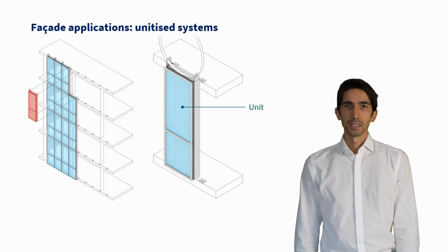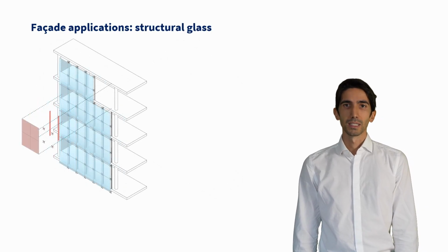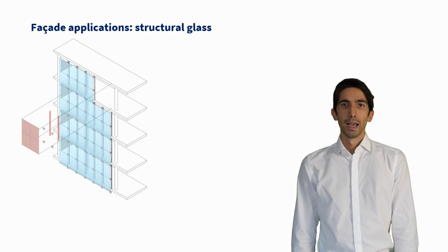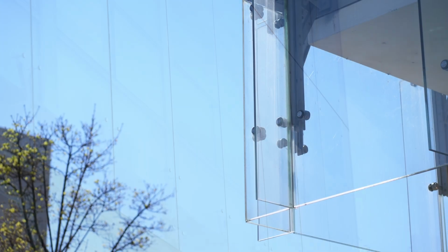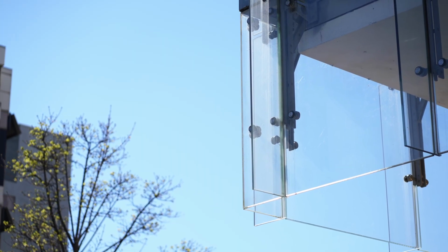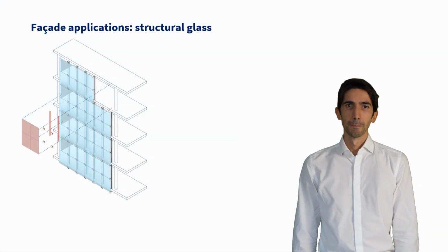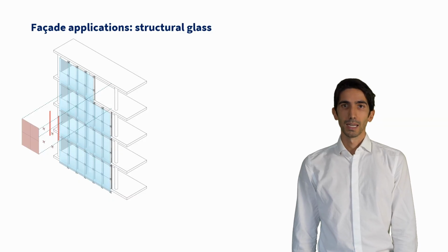Finally, the structural glass facade is composed of an interior load-bearing structure, which can be realized in many ways, and a glass pane that is directly connected to this structure without using continuous gaskets and external pressure plates or caps, as described in the stick or unitized systems. The inner structure can range from glass mullions to steel fins, cables, rods or aluminum mullions, while the outer glazed facade can be realized using monolithic laminated, double-glazed or even triple-glazed insulating glazing units. The air and water tightness are guaranteed thanks to the use of high-performance gaskets and sealants.